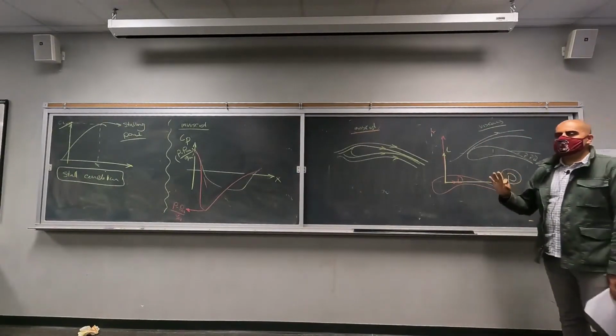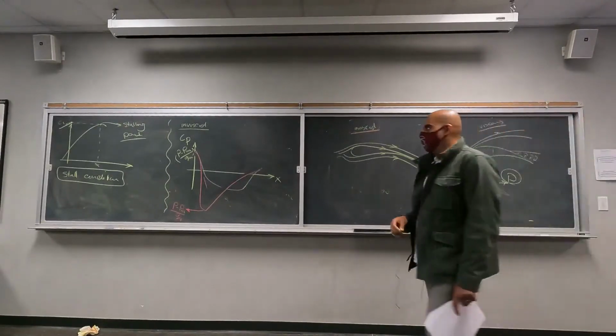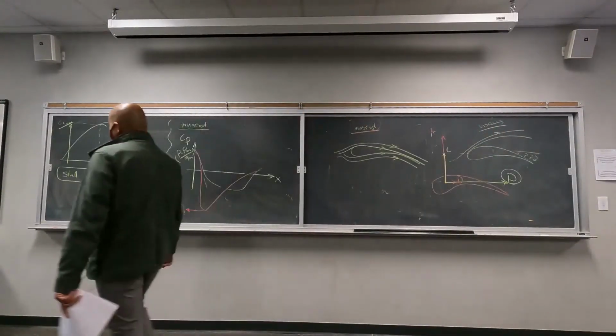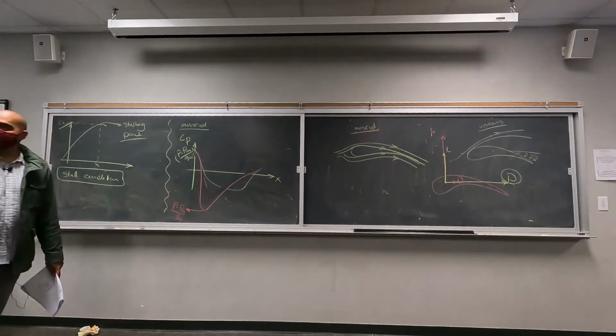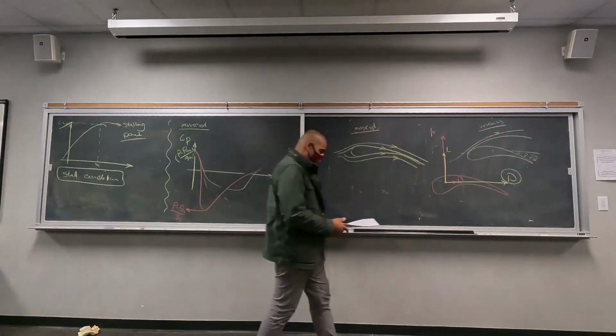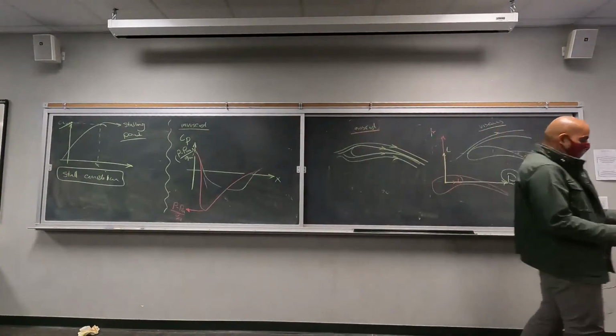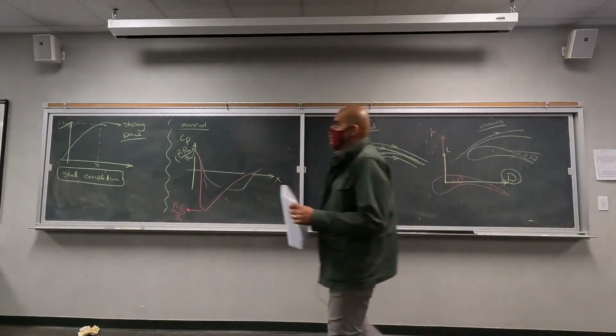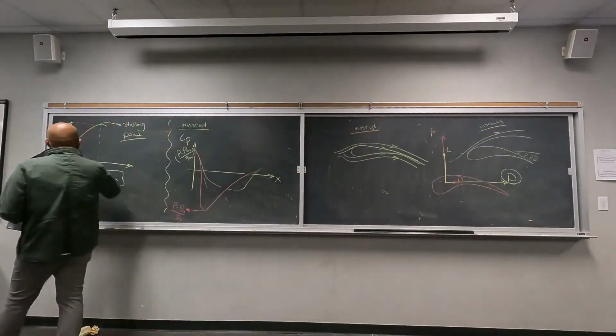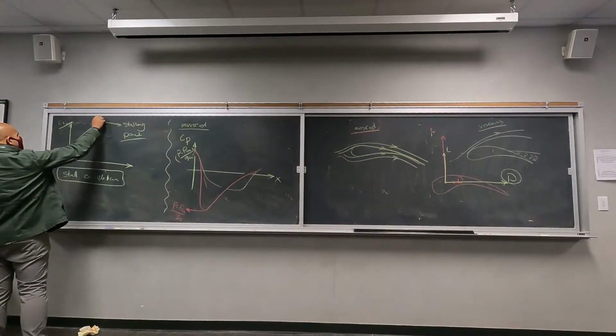We want to see what the different types of stall conditions are now. We want to see what methods we can employ to change the stalling point, to change the angle of attack, or to increase the lift, if it's even possible to do so. But before moving on, let's see how we can calculate the stalling velocity. So we want to see what the speed will be here.